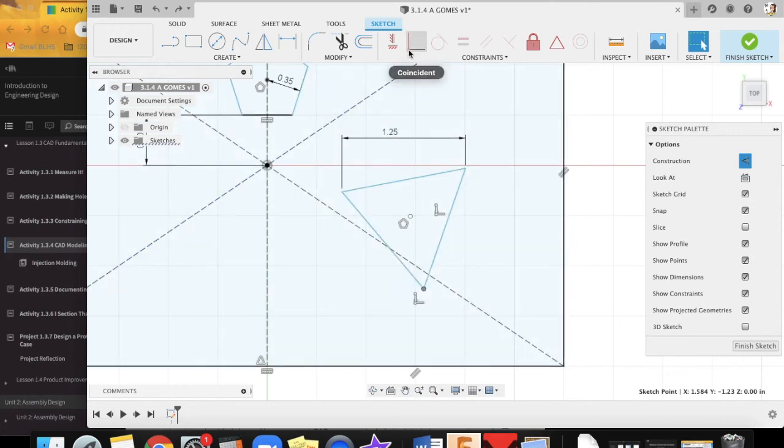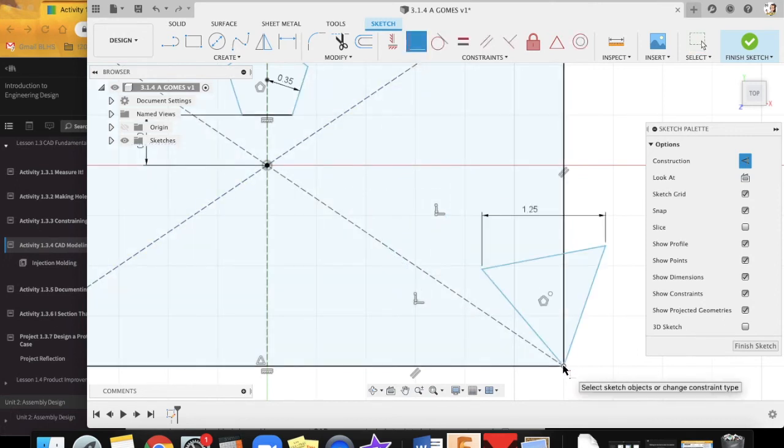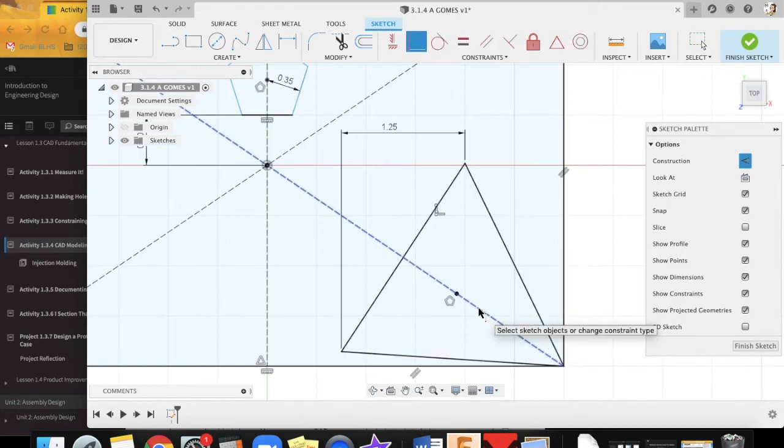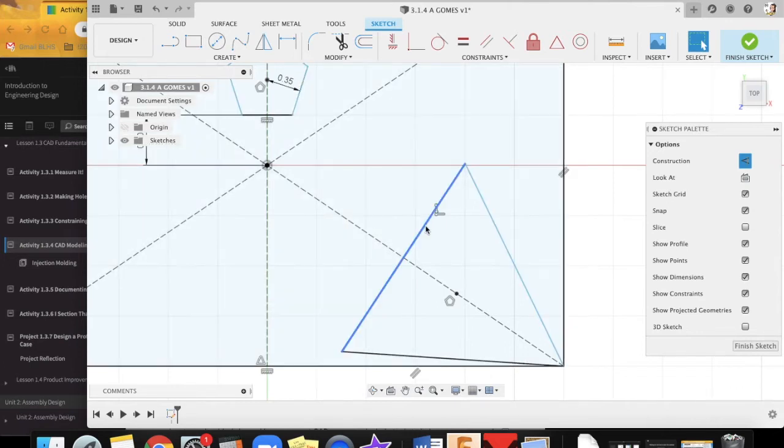Okay, finally, I'm going to try to just go ahead and constrain it the way that I'm supposed to and constrain that center to the diagonal again. And it's still making that error. And so I finally decided, well, maybe I just need to delete that dimension and then dimension the side instead, and that's where I do it properly.